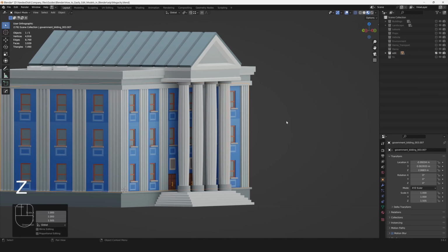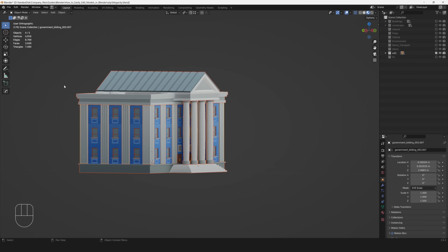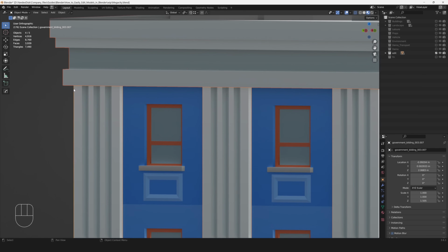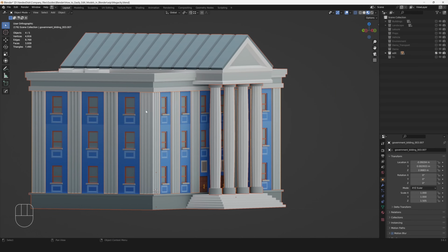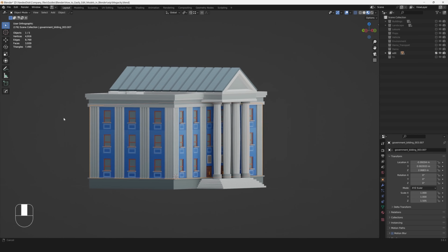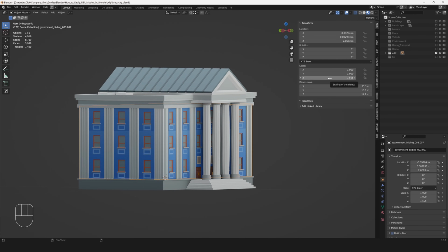Here is one thing you should notice. As you can see, there is one yellow object and others are with an orange outline, and the one with the yellow outline is meant to be the main selection, so the last one, and every other object will be joined to this object when you press Ctrl G or any other function to join objects.